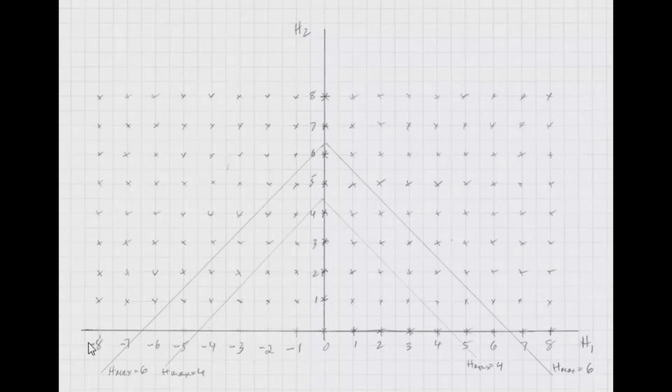There are negative values of F1 because you could have, say, 2F2 minus F1, and there's really no need to have the part of this plot that is below the x-axis because those frequency components are the same as ones from the upper part. So 3F2 minus F1 is going to be the same as F1 minus 3F2. It's just a negative value. And for the sake of frequency selection, they're the same.